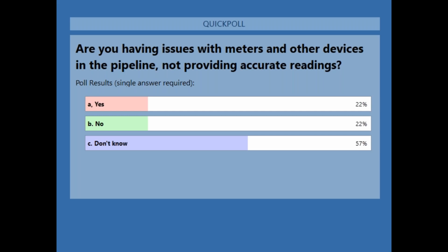The cause is probably air before your meters. If you've got air going through with your flow, it's not going to give you an accurate reading, because you could have 2, 3, 5, 6% air in the media, and it's going to cause some false readings.